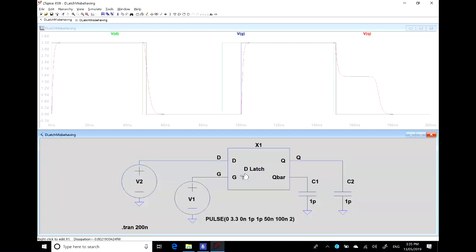So while you're thinking about that, I might just expand. If I have a D-type flip-flop, roughly speaking, the same thing happens. That D-type flip-flop's output circuitry is going to latch the value by basically having two inverters connected in a loop, like we showed you before, the same as this latch.